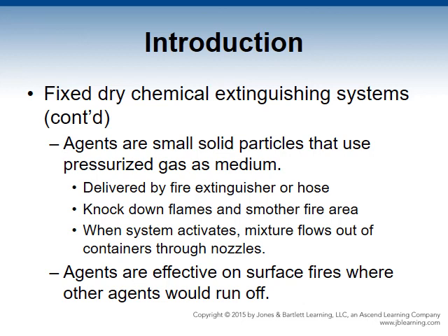After the system activates, the particle and gas mixture flows out of the container through the nozzle. The nozzle type and placement depends on the hazard and its protection requirements. These agents are effective on surface fires where other agents would run off before they could adhere.